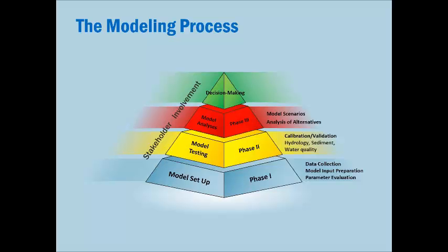And once you've completed the calibration, then running that model on a different time period and performing a validation step. And this is what we often refer to as model testing, trying to gain confidence that the model is representing what your watershed is, and gaining confidence in that representation based on the calibration and validation results. If you can get comparable results during the validation period as you did during the calibration period, then you can have confidence that the model is a good representation of your watershed system.